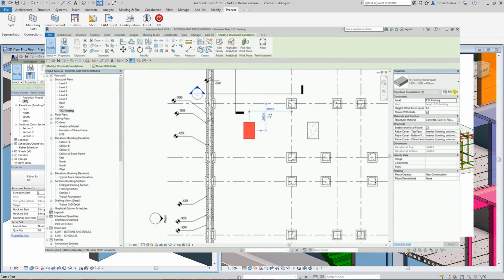And clicking on those dimensions will then allow me to move those objects, because this object has that relationship between those two grid lines for me to be able to position that element. So instead of saying, offset that grid line 4 meters to the left, then offset it by the width of the pad footing, maybe draw me in a rectangle, or offset from the other grid line back 2 meters to find the center in the other direction.